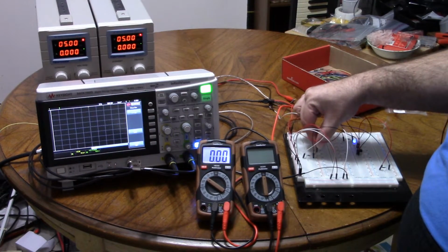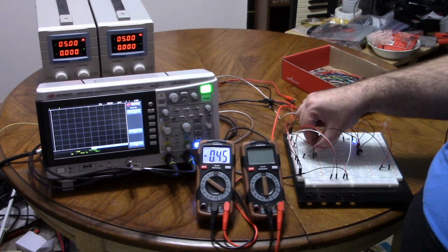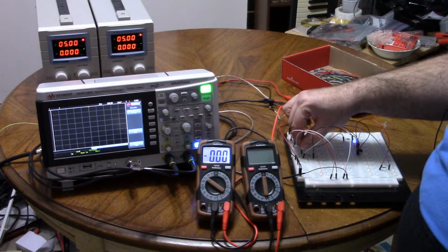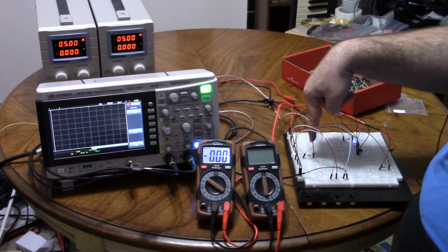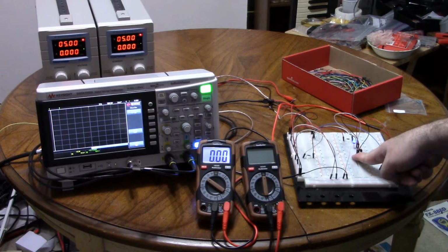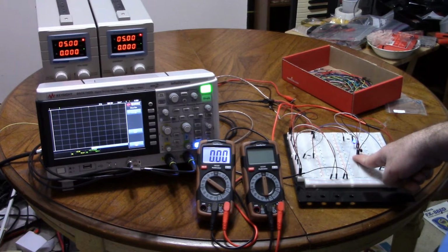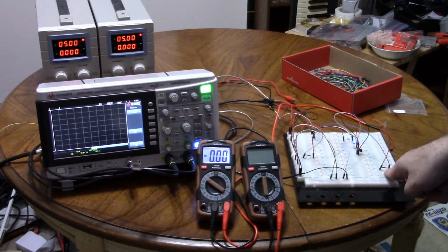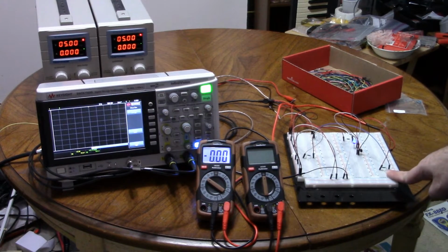If I measure the signal resistor, on the right is minus 0.45, on the left is straight 0. So there's a small voltage drop on the signal resistor. So at 0 signal, the base is slightly below 0, and then the further voltage base to emitter from that, and then the emitter resistor is taking whatever it wants to take based on Ohm's law.